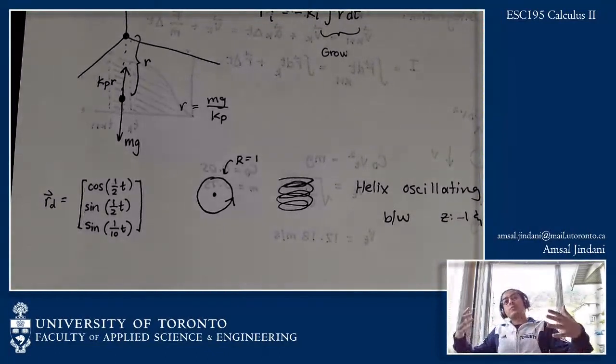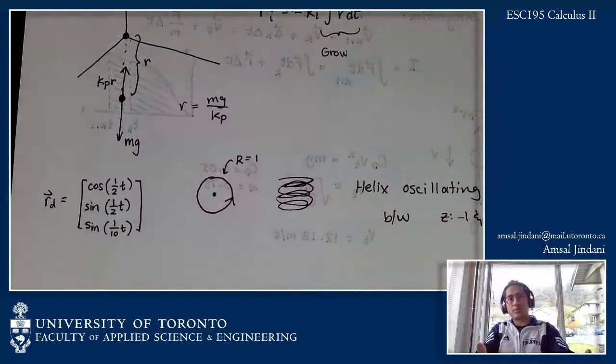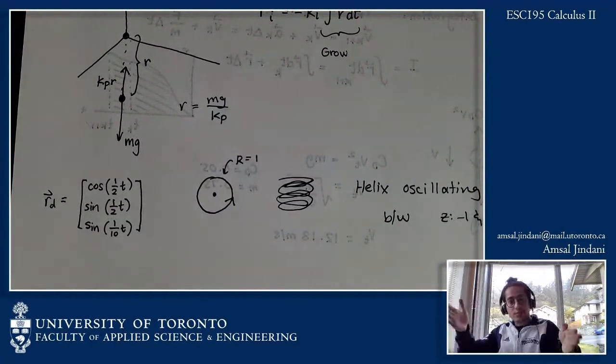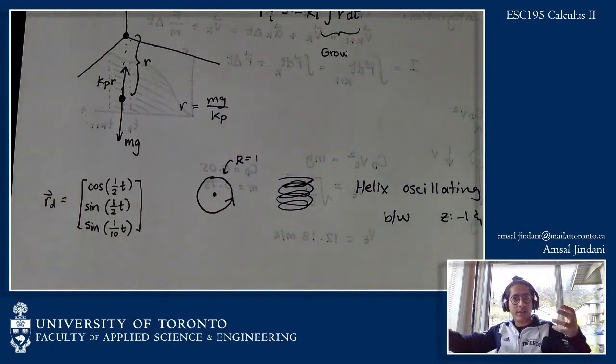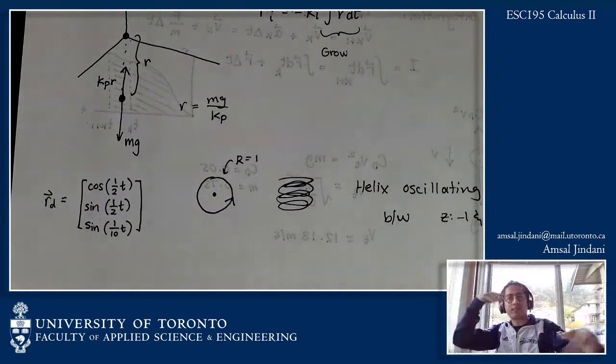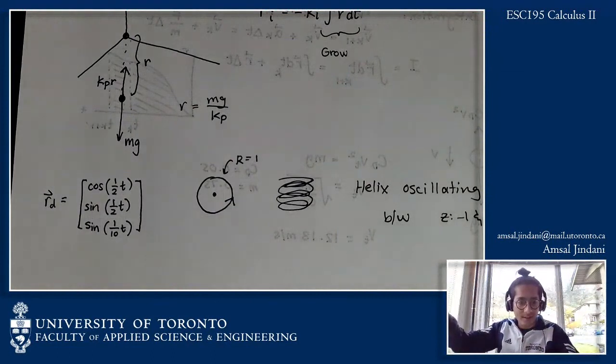So on drones, not only do you need positional control to control the position, you actually need orientation control, because the drone has to be able to keep pointing at the object that you want to film. So there's actually two control systems going on at the exact same time, one to control the position, one to control the orientation. And they're actually not separate control systems. They have to communicate with each other, because the way the drone is oriented affects the thrust and drag and so on.